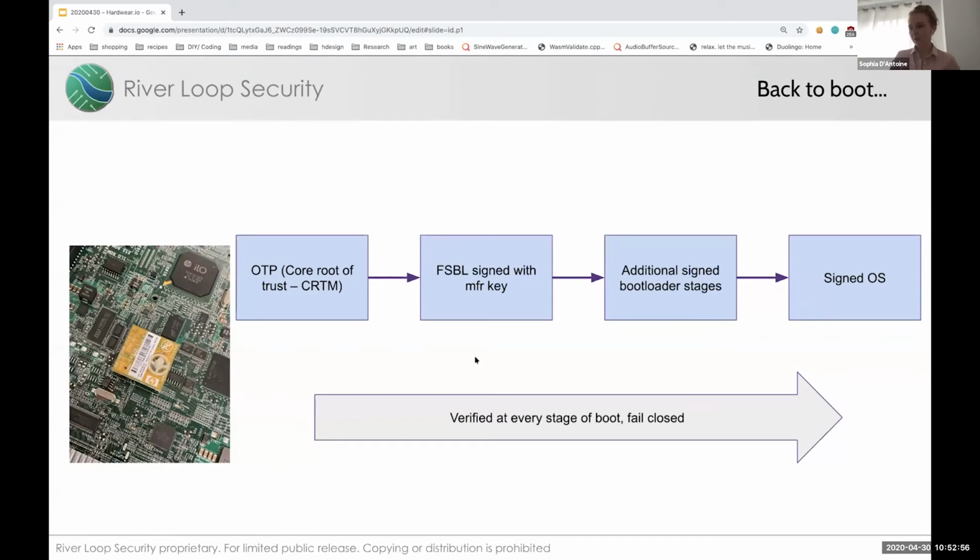And so by definition, the TPM is a root of trust of a given system. And it's trusted because its correct operation cannot be verified by that system. So in general, for a CRTM to operate correctly, it must be immutable for the system that relies on it. This just means that this part is considered trusted and can't really be verified by the person auditing or by the person reverse engineering the board.